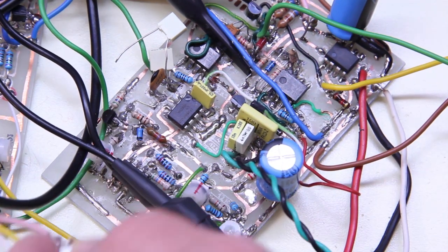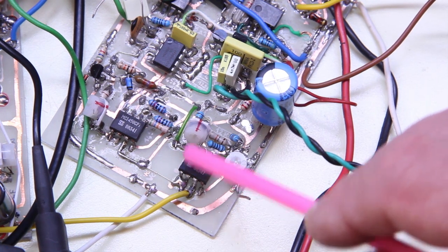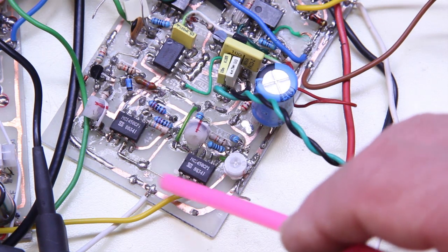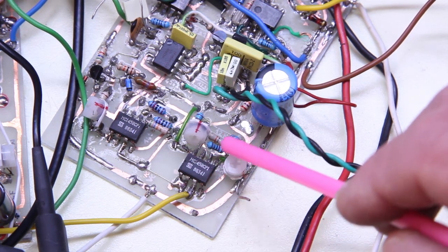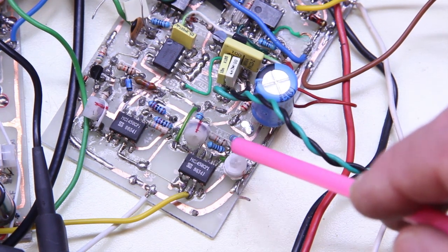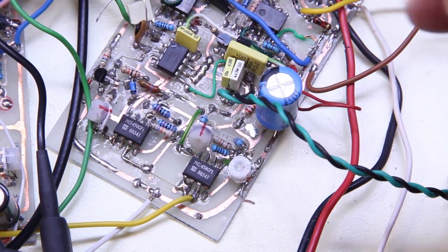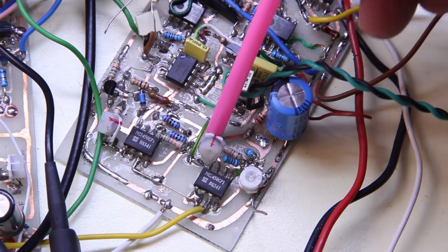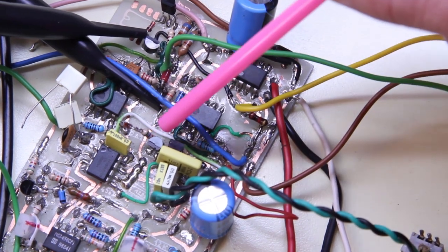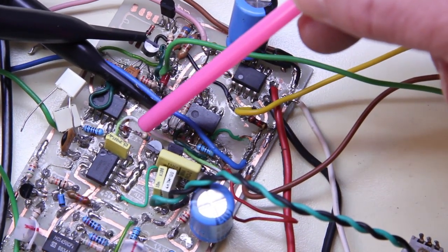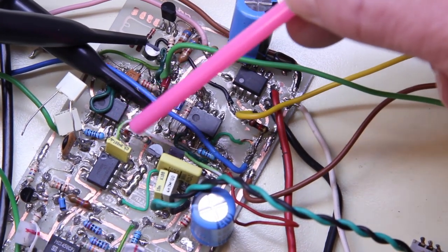Here we have the voltage control through the potentiometer that enters here, where we have the 1458 operational amplifier, here the voltage follower, and here the inverting amplifier with the two potentiometer trimmers to adjust the gain and bias, and the signal then is fed through this 100 ohm resistor to this switch transistor, and this is the current source transistor, the 5.6 kilo ohm resistor here, and the two diodes here to create the voltage drop.